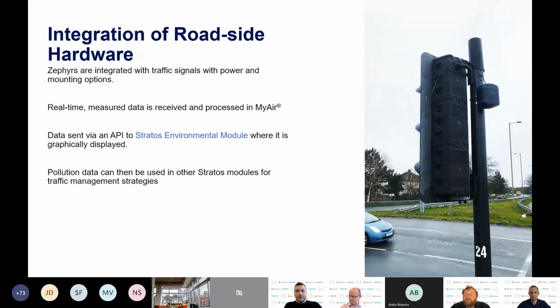And the Zephyr can now be very, very quickly and easily deployed with minimal on-street work, assuming that you have spare cores at your pole cap. It's a very simple installation of being able to wire into that pole cap and then install the power supply inside that controller. So that's the physical integration that we've done to try and make these as easily deployable as possible within that transport setting.